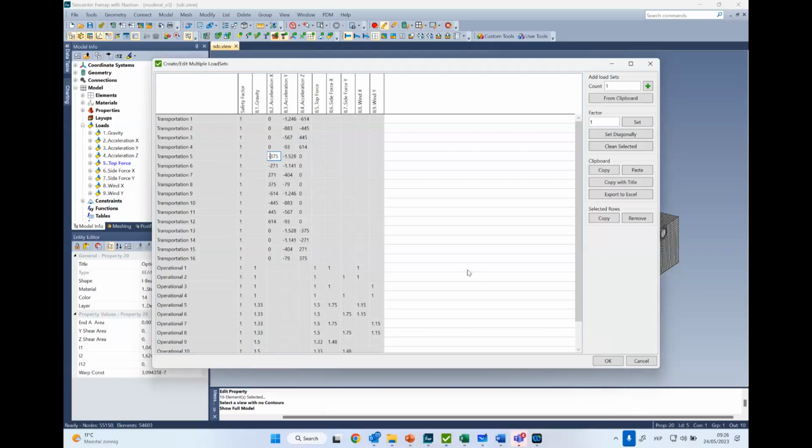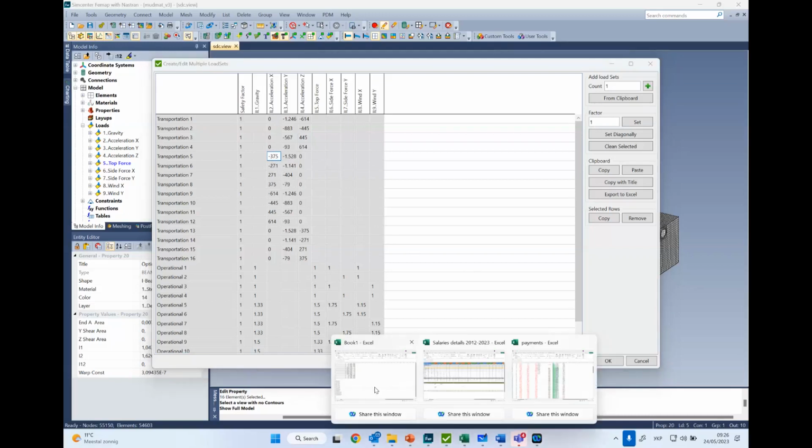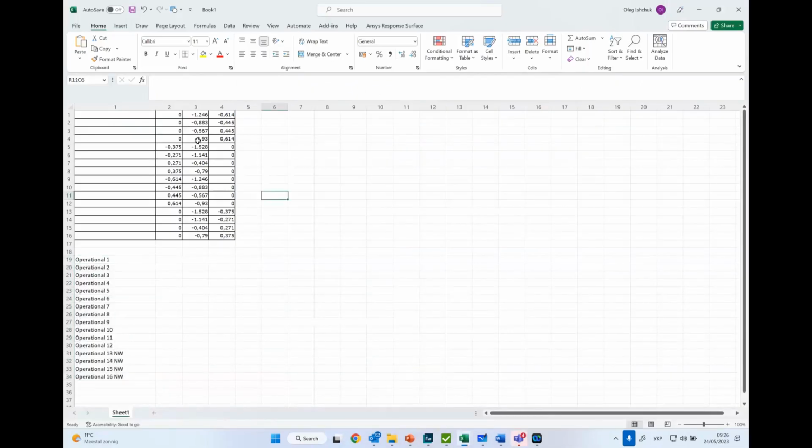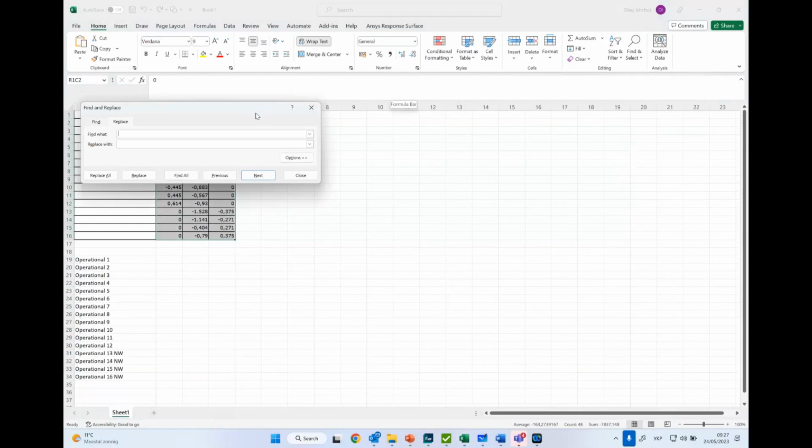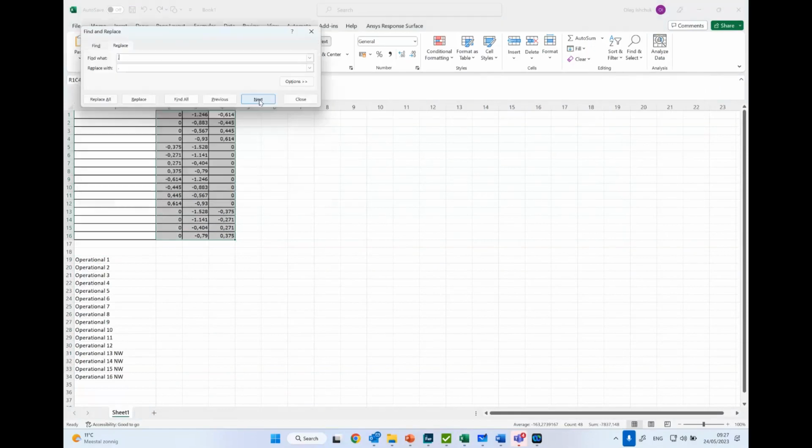And I think when it was exported from Excel, in this case, we have comma in some cases, and that comma was not read well. So this is also one of the options. What you can do, I'll show you very quickly over here. So first of all, I have to modify our cases, right? So I'll do replace, and I will replace the comma with the dot in the text. Press next. Replace all. Yes, all the replacements are done now.